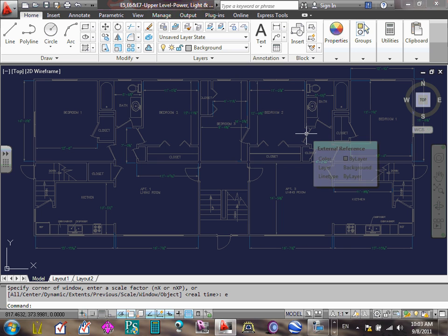It really doesn't matter because we're not referencing it. Usually, when we bring in the extract, it tells you where you want to insert it, and the one that's clicked says 0, 0, 0. It should be 0, 0, 0. It makes a big difference when we're doing Revit and coordination, but for what we're doing right now, honestly, it doesn't make a difference. Otherwise, you can delete it and extract it again at 0, 0, 0.